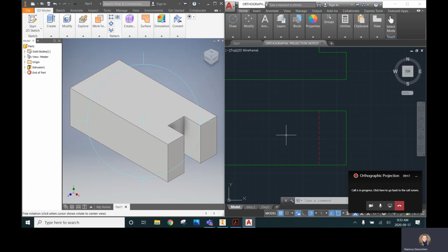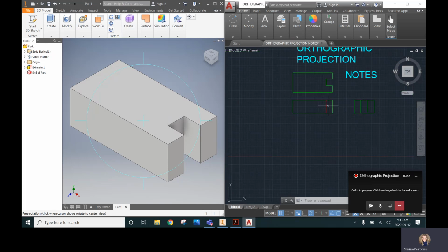So I think as far as drawing in orthographic goes, it's fairly straightforward. It's just determining where the hidden lines are that gets a little bit tricky. Maybe you have to think, okay, there's that feature, but can you see it? Often it's for things like holes and edges and chamfers, and you don't know what a chamfer is yet, but just features on a drawing that you need to highlight. So in this case, there's a notch that runs all the way through, so you put a hidden line to depict that.